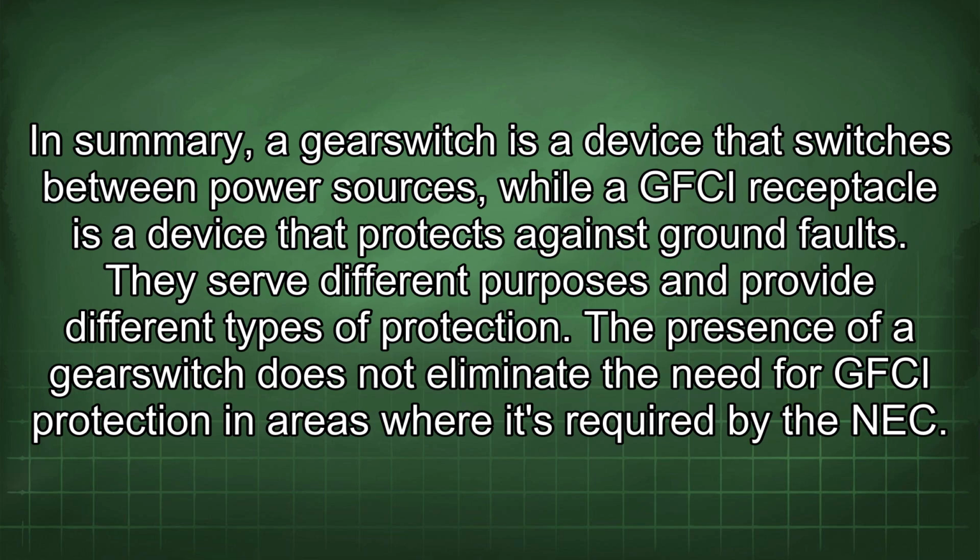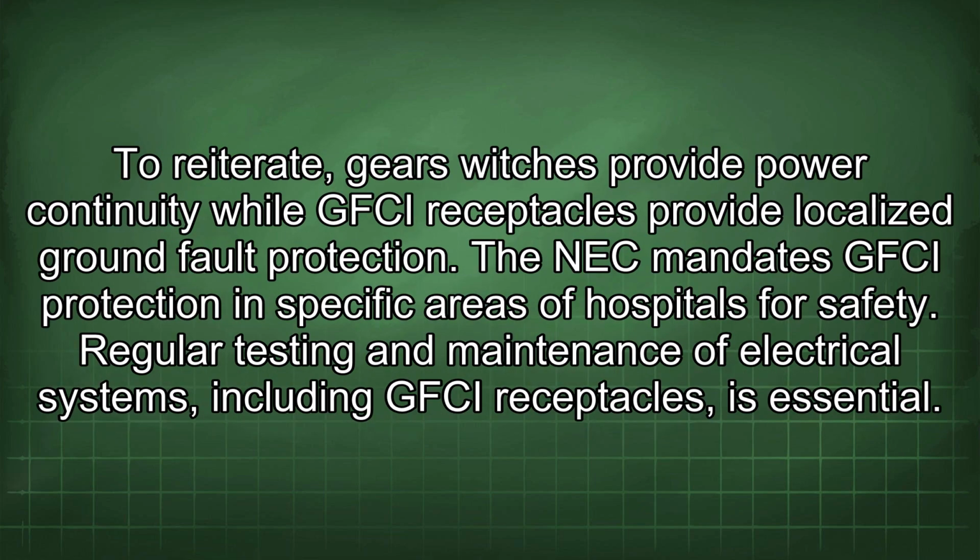In summary, a transfer switch is a device that switches between power sources, while a GFCI receptacle is a device that protects against ground faults. They serve different purposes and provide different types of protection. The presence of a transfer switch does not eliminate the need for GFCI protection in areas where it's required by the NEC. To reiterate, transfer switches provide power continuity while GFCI receptacles provide localized ground fault protection. The NEC mandates GFCI protection in specific areas of hospitals for safety. Regular testing and maintenance of electrical systems, including GFCI receptacles, is essential.